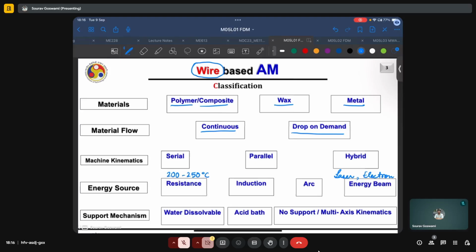However, we saw that when such a multi-material functionality cannot be availed or is absent, what we can instead do is make the support structure weaker, either say in the case of UV based processes where we printed both the build material and support material but did not fully cure them, then broke off the support materials manually and then put the part for the final curing process. Or we can have some design strategy whereby we deliberately make the support structures weaker or less dense so that they are easier to break off.